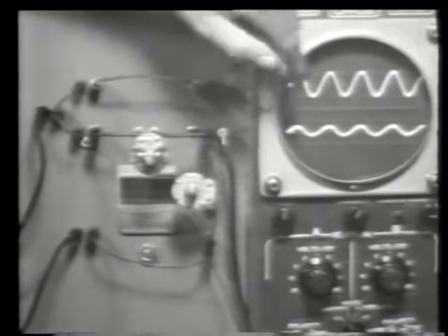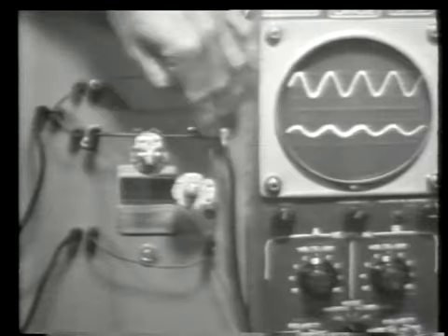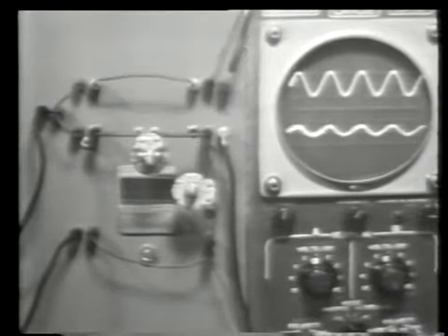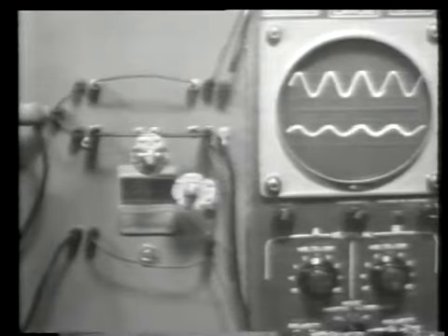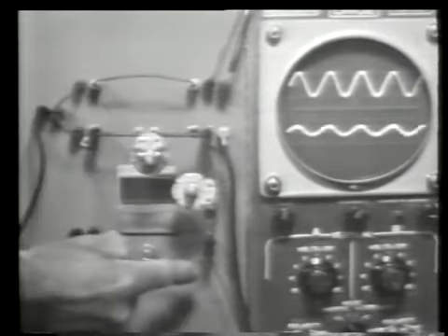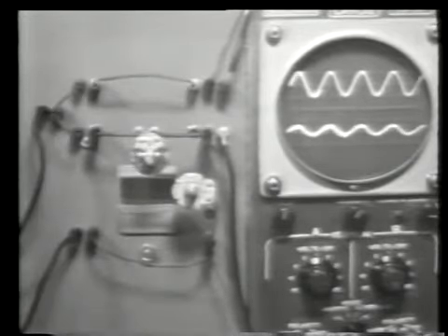You'll also be able to see the output displayed on our scope, so you'll have two checks to determine the effect of our filter components on our output voltage. I think in this way you'll be able to understand the operation a little better. Now remember, the generator output, which is applied here, will go through the series component, then down through the shunt component to ground, and we'll be taking our output across the shunt component.